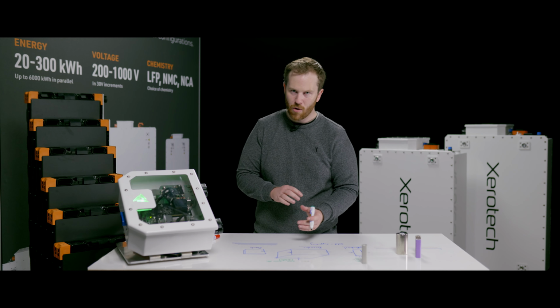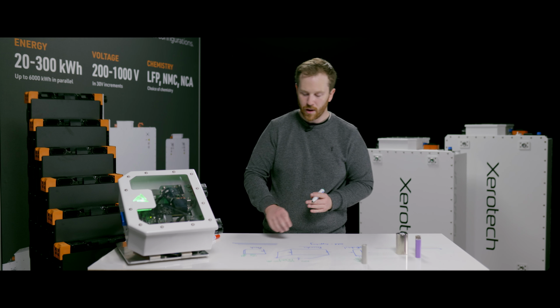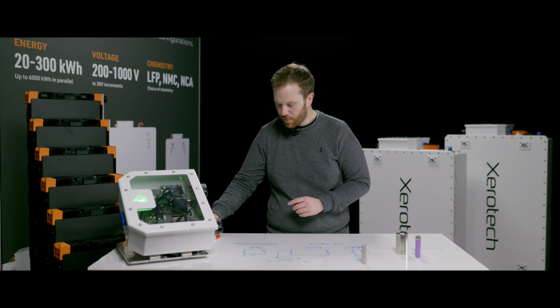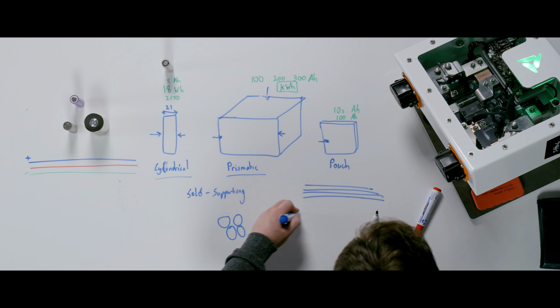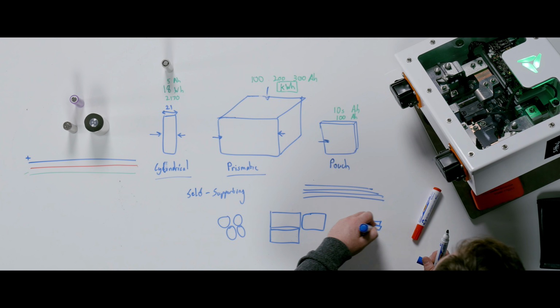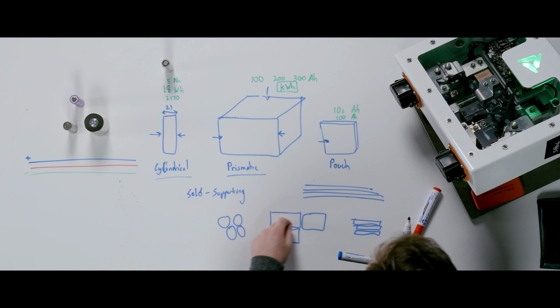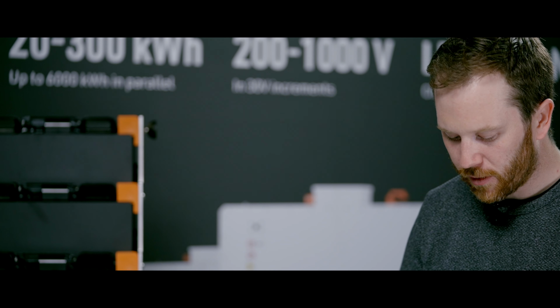Likewise with pouches, they vary, but they can be quite big. They could be tens of amp hours, if not even 100 amp hours and above for large pouch cells. This is a lot of energy. So in the event of a thermal runaway in a real battery pack where you've got lots of cylindrical cells packed together or lots of big prismatic cells packed together, or even pouch cells, if you've got large units of energy, and if one of your units of energy fails for whatever reason, it is extremely difficult to contain that energy. No amount of technology is really effective.